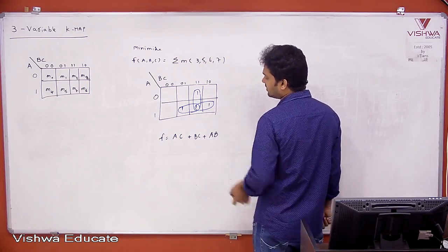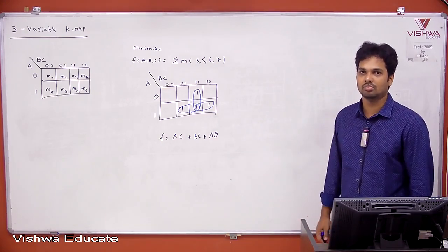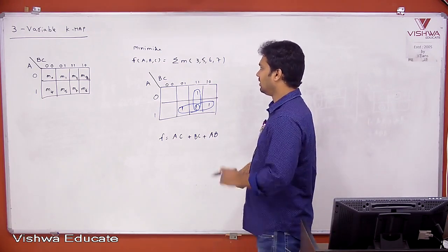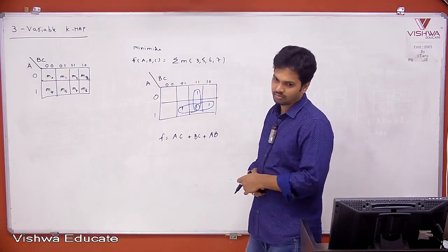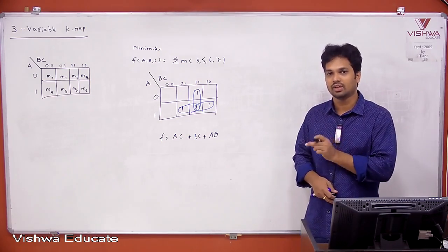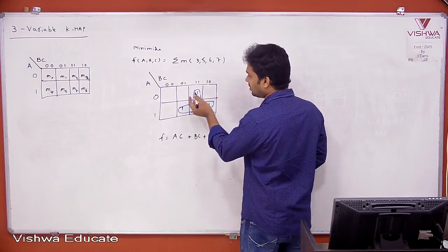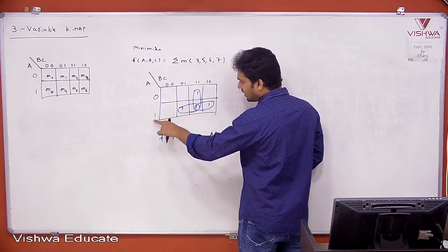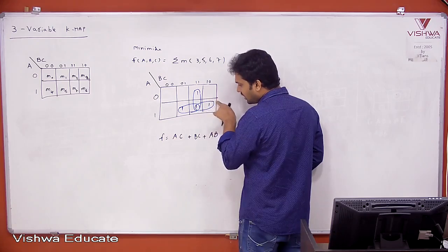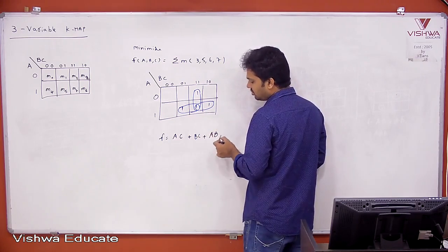It is already we discussed. What is this gate? This is called majority gate, we discussed in the Boolean algebra. There also, if you remember, I have the expression A bar BC plus A B bar C plus ABC bar plus ABC. We added ABC 3 number of times, ABC plus ABC plus ABC, to get the solution. Here indirectly you are doing the same. In this pair, what is this term? A is 1, B is 1, C is 1. So this term is called ABC term. ABC term is taken 3 times to get the minimized solution.